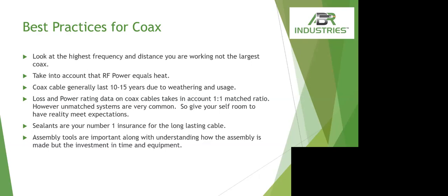Also, with a lot of the radios using tuners, the multi-tuner devices that are out there, the ones in the radios can start at 3:1, but a lot of them go much, much higher, up to 12:1, and even a little bit higher in some of the other practical applications. So give yourself a little bit of room, because as your tuner mismatches to find the perfect match, there's going to be some heat buildup.